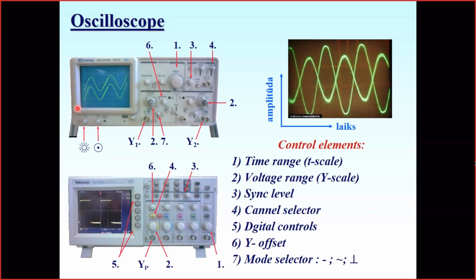A very important thing in an oscilloscope is so-called synchronization. Imagine that we draw some graph on the oscilloscope screen, and then it starts to draw it from the beginning once more. Usually we get the situation when the next drawing overlaps the first drawing.